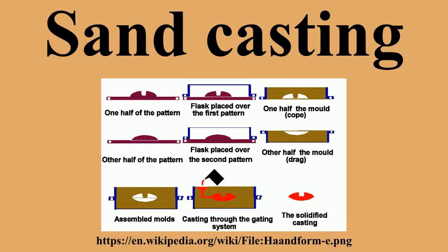The method, like DISA's vertical molding, is flaskless, however horizontal. The match plate molding technology is today used widely. Its great advantage is inexpensive pattern tooling and ease of changing the molding tooling, thus suitability for manufacturing castings in short series, which are typical for the jobbing foundries.